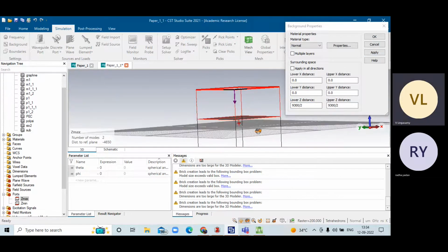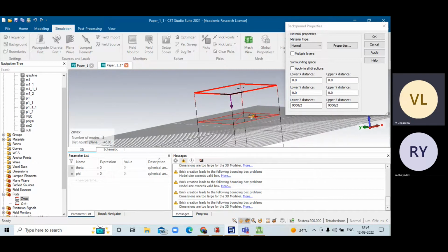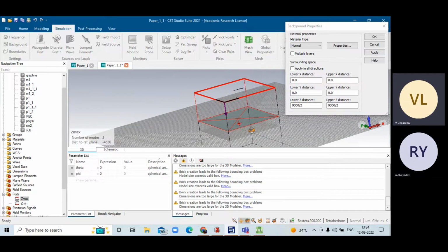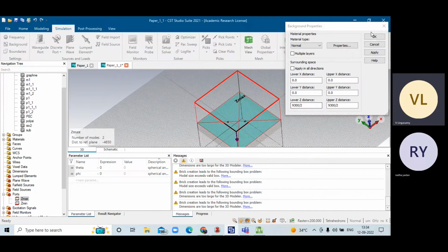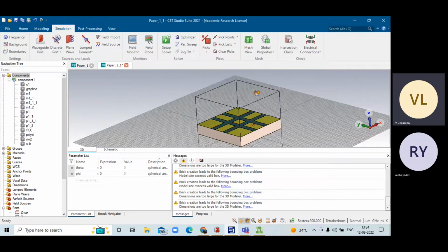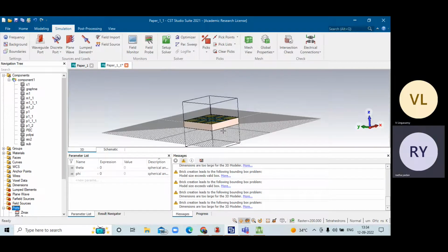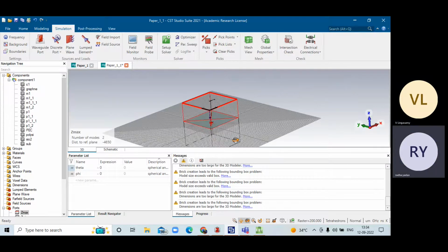Can you see here? No, because it is taking 30 gig as the center frequency. 1 to 60, right? So it will be taking 30.5 usually by default. Now we can put like this. Okay, cancel this. Click OK. That's it. So now it's fine. Now we can start simulating this one. No problem. Where is Zmax? It is here.